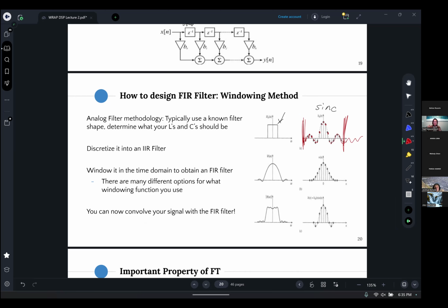And then there are also a couple of different windowing functions that you can use that maybe weaken some of the points towards the end, for example. So you can have smoother transitions, because if we're in the middle of the signal right here and then we drop it to zero immediately, that might have some effects on the effectiveness of our filtering.